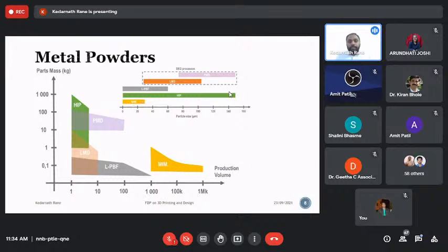For metal, you can get this powder particle size easily. But for the powder manufacturing process for ceramics, even a 20 micron particle size is difficult. So in the domain of powder injection molding, the particle size is favorable from 0 to 5 microns. That is the favorable particle size for ceramic powders.